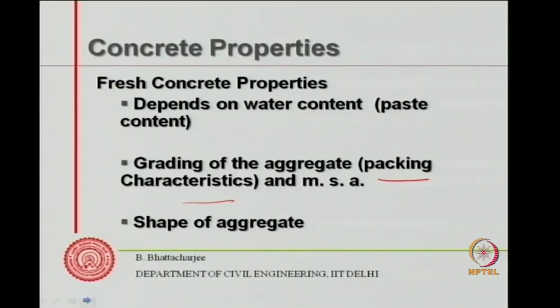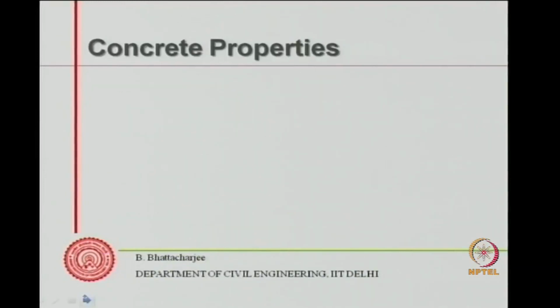The strength is not governed by shape. If anything governs, it would be the structure of those aggregates, but not the shape. Shape governs the packing characteristics. So these are the factors which will dictate how much water or paste is required.